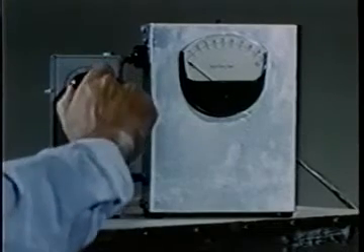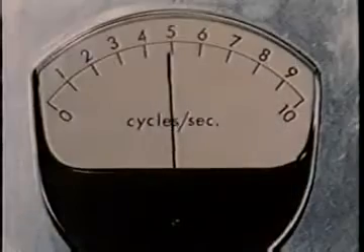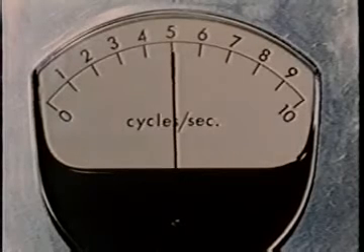We start the wave maker oscillating at 5 cycles per second. At 0 airspeed, the waves damp as they travel away from the wave maker. With the tunnel running, but below critical airspeed, we don't notice much change in wave damping. As we increase the airspeed and pass critical speed, we see the waves grow.